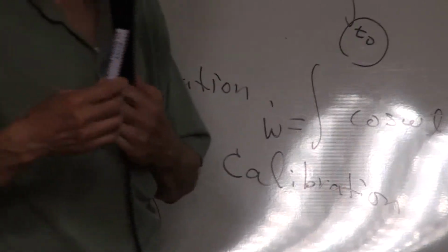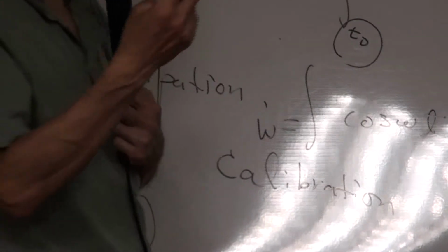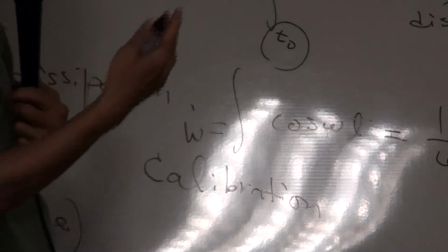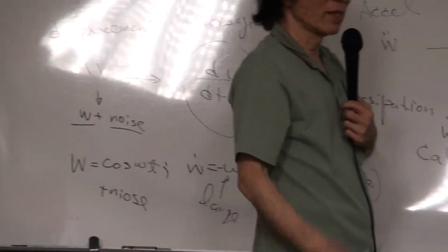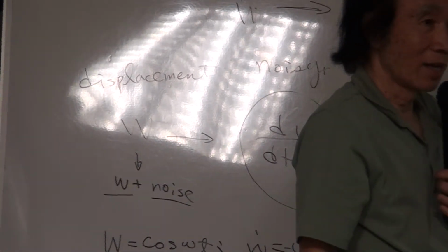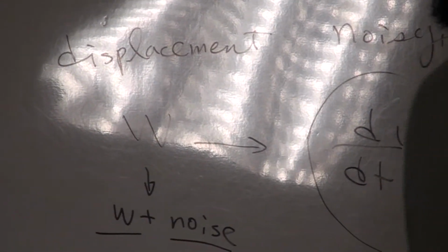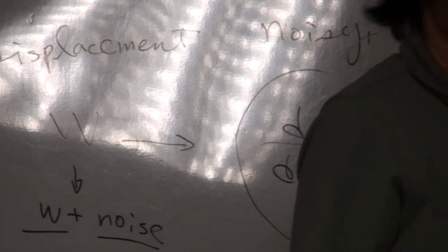So in space applications, most likely they will use two kinds of sensors. One sensor is just for calibration. One sensor is for integrations. So you can have a gyro, or you can have an accelerometer and integrate to get some information. And then I can have a star tracker to calibrate. Right?